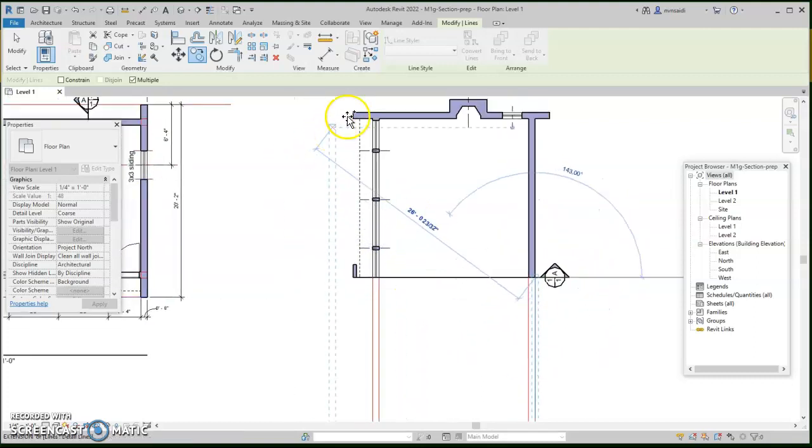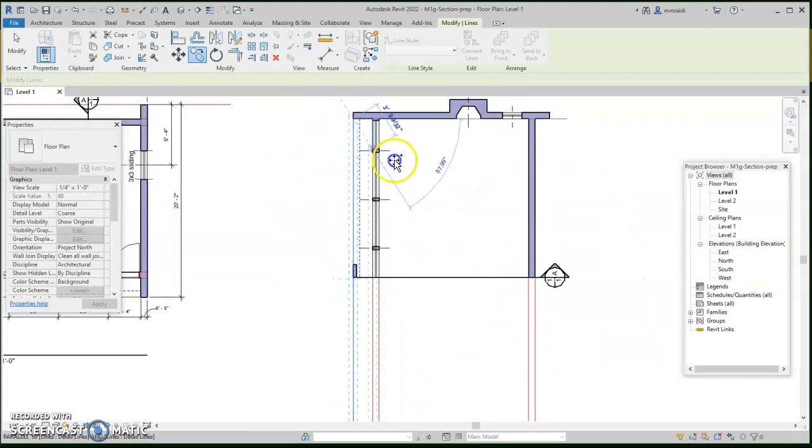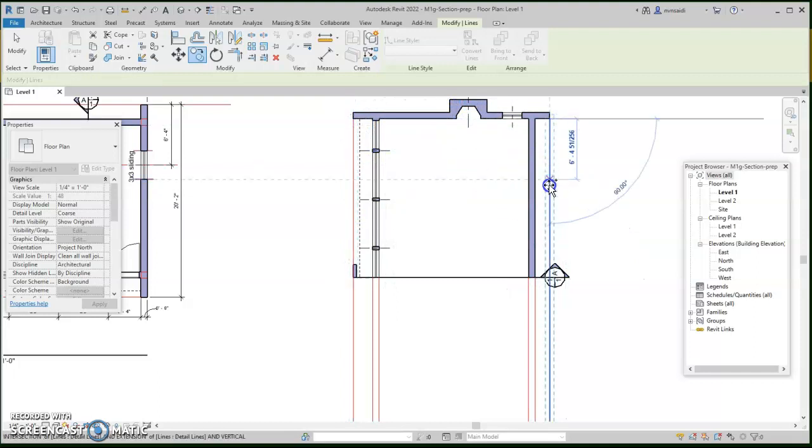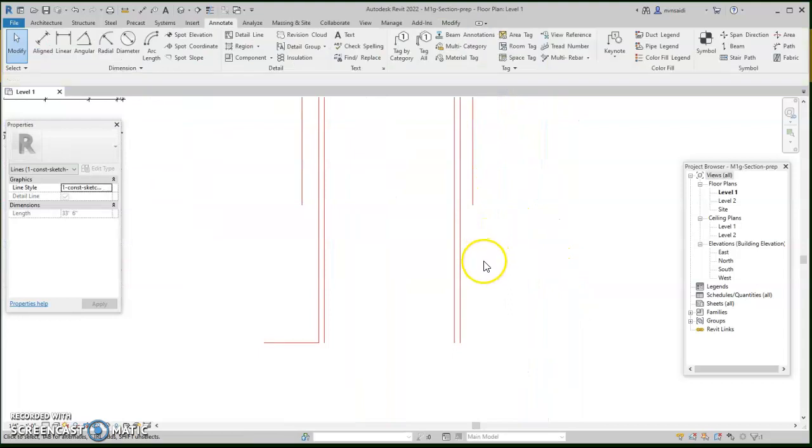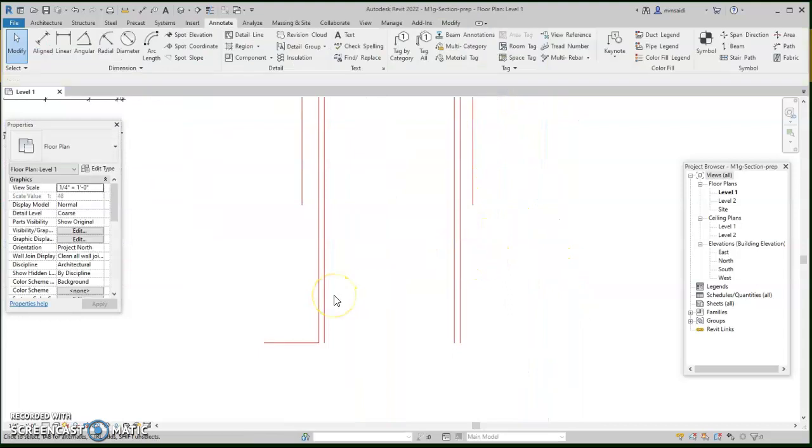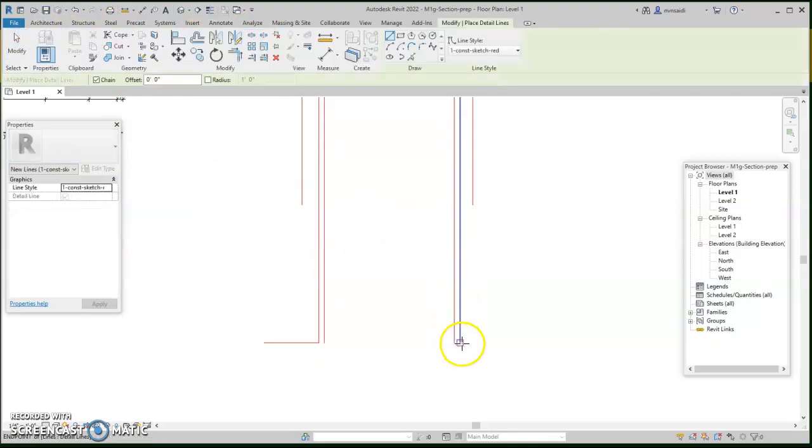Now I'm going to identify the outline of the wing wall in the background that I get to see. So essentially these are the two walls that I'm cutting through, and that's the outline of the section. The ground line is on this side, so I'm quickly going to sketch the ground line from this junction. Doesn't matter, just a good distance over. Okay.